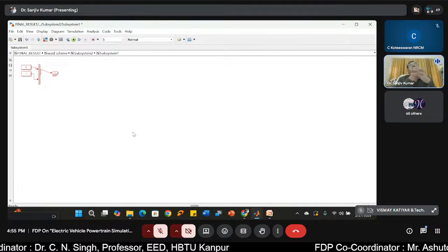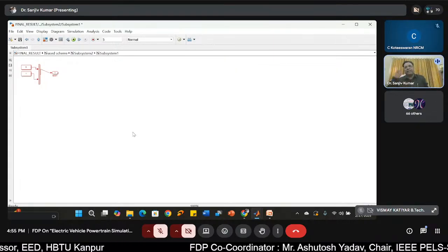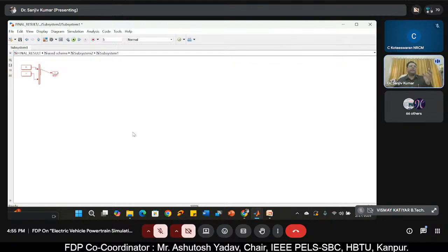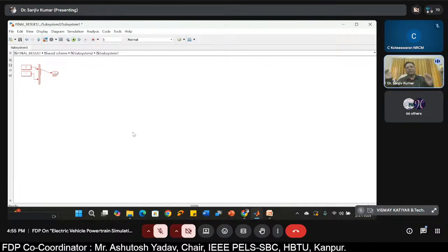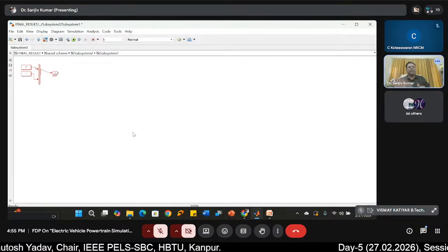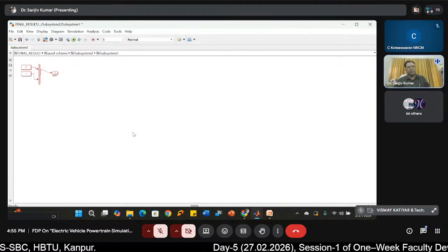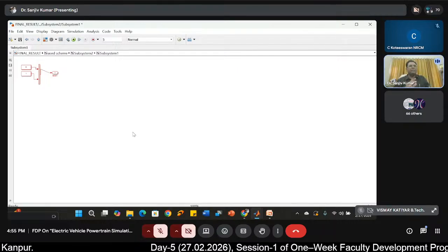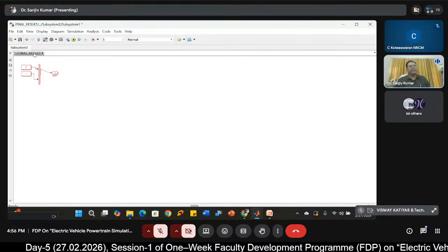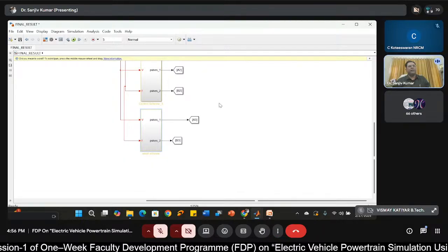If you remember, the two level inverter had a left hand side and a right hand side. So for pole voltage, one has to be either plus VDC or 0, and the right hand side also plus VDC or 0. So two switches are to be operated and the remaining switch of that particular leg will be operated in the complementary fashion. If it is 0, then the lower switch would be 1. So that things are to be done.